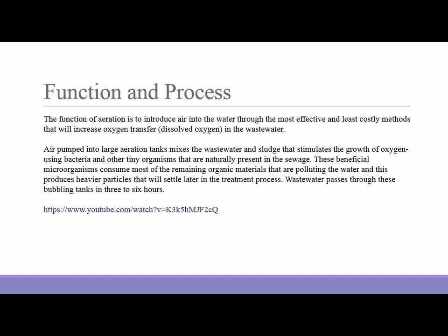So the process of aeration is that air pumped into the large aeration tank mixes the wastewater and sludge, which stimulates the growth of oxygen-using bacteria and other tiny organisms that are naturally present in the sewage. These beneficial microorganisms consume most of the remaining organic materials that are polluting the water, and this produces heavier particles that will settle later in the treatment process. Wastewater passes through these bubbling tanks in 3 to 6 hours.